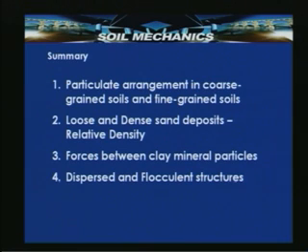An important parameter, relative density, has been defined for coarse grained soils, and we also deduced the reasons for different arrangements of dispersed and flocculent structures. The forces between the clay minerals, with van der Waals forces of attraction and repulsion forces between two adsorbed water layers, which may determine the forces between the clay particles, have been discussed, and these yield dispersed and flocculent structures.